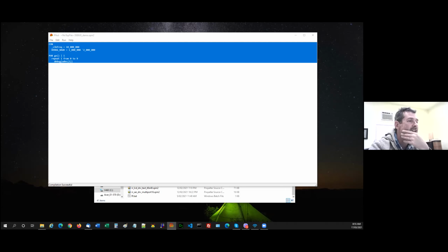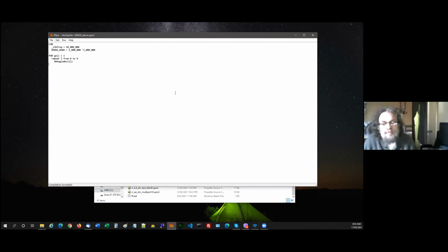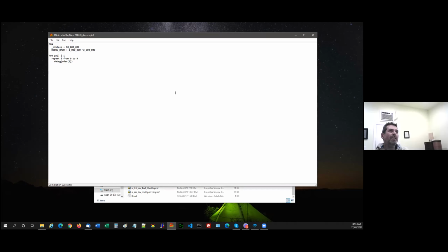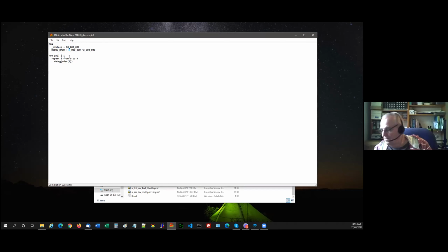Also, maybe your other chip is just using the standard baud rates and not something like 400 baud or 2000, or it has to be a multiple of whatever. Maybe multiples of that, you know. Yeah, maybe yours doesn't have that timing option. I even got it going down to 600 baud, but this is using a P2 eval. So I think there's an FT232 on that board, isn't there?